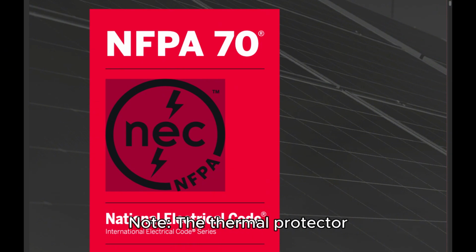CMP11 informational note. The thermal protector may consist of one or more sensing elements integral with the motor or motor compressor and an external control device. Thermally protected as applied to motors. The words thermally protected appearing on the nameplate of a motor or motor compressor indicate that the motor is provided with a thermal protector. CMP11 unclassified locations as applied to hazardous classified locations.